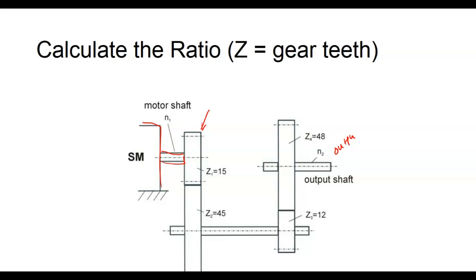So how much torque would we get out of the first set of gears on the left? So we'll call it set one would be equal to 45 over 15. Is that diameter or is that radius or that T? Don't make any difference, right? You understand that? So we get a mechanical advantage of 3. Okay, over here, I got 48 out, 12 in. The mechanical advantage would be what? 4. So what would be my total mechanical advantage?